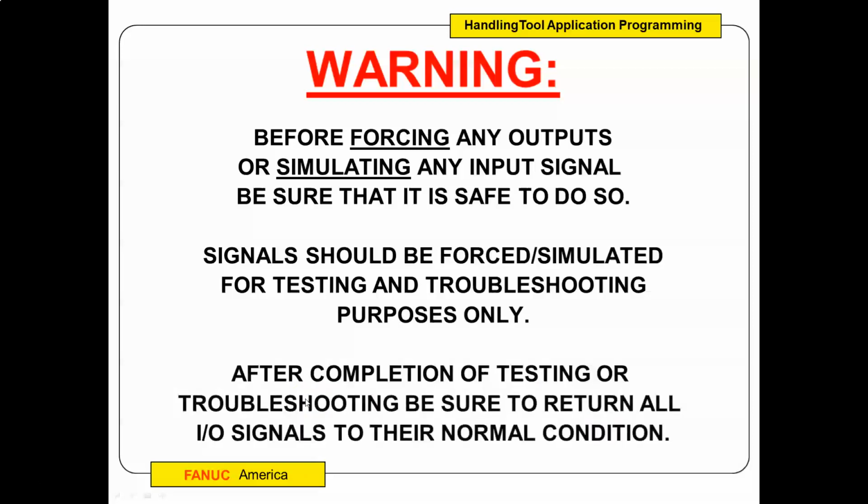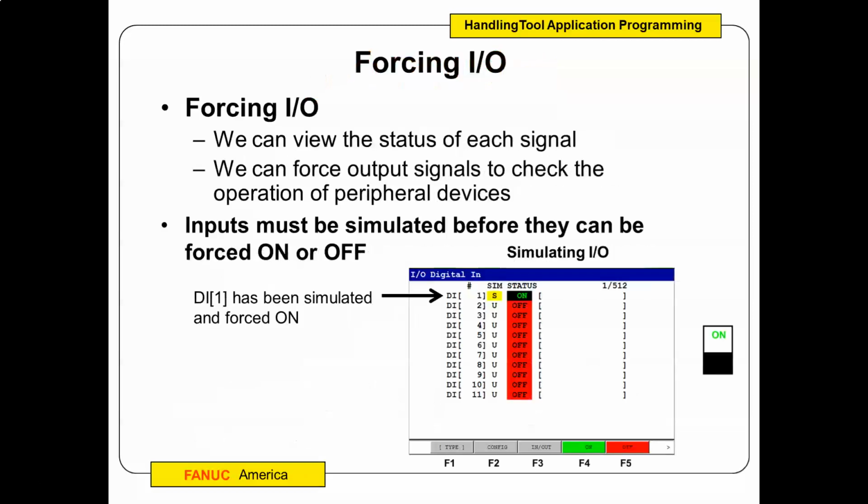Make sure that when you're done troubleshooting, you unsimulate all those things. Otherwise, if you're waiting for that operator push button and you leave it simulated on, then everything runs again, and instead of waiting for the operator button, because it's already simulated and forced on, it will just go ahead and say, yes, it's already pushed, and go forward. So you need to be careful of that.